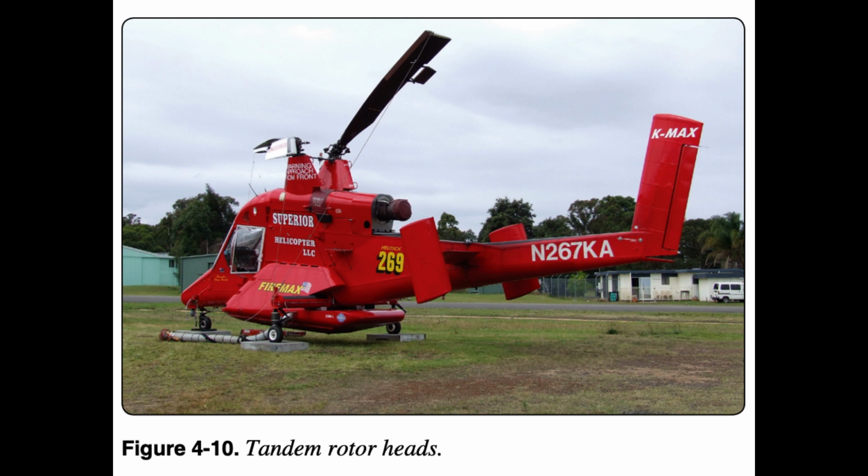Figure 4.10. Single rotor helicopters need an anti-torque system to neutralize the twisting momentum produced by the single large rotor. Tandem rotor helicopters, however, use counter-rotating rotors, with each canceling out the other's torque. Counter-rotating rotor blades will not collide with and destroy each other if they flex into the other rotor's pathway. This configuration also has the advantage of being able to hold more weight with shorter blades, since there are two sets. Also, all of the power from the engines can be used for lift, whereas a single rotor helicopter uses power to counter the torque.